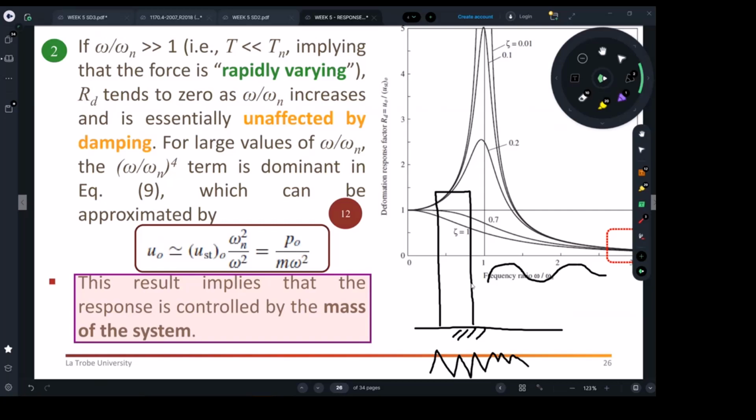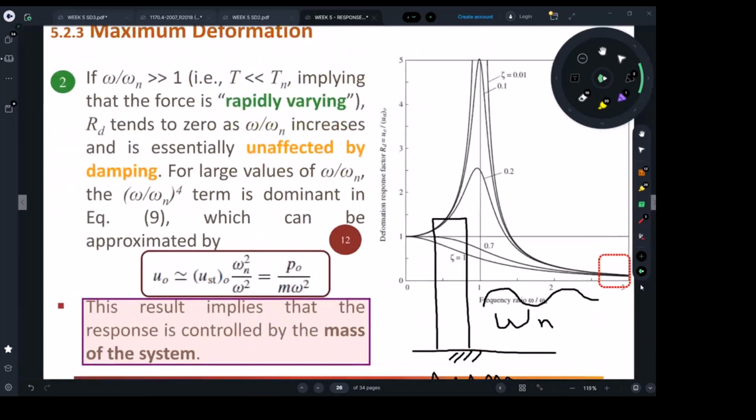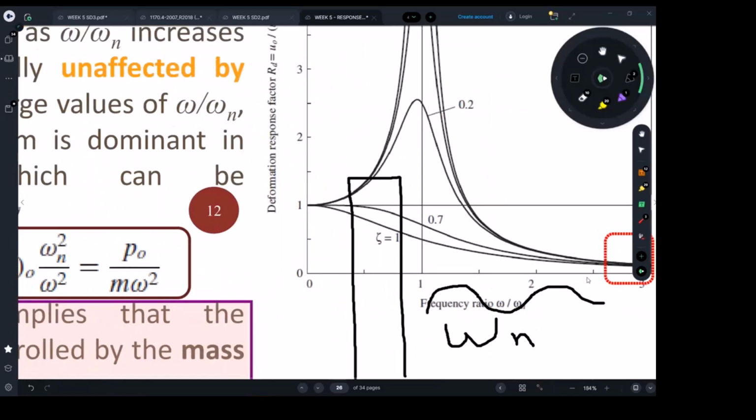So you've got a building whose natural frequency omega n is kind of gentle, and the forcing frequency is very high frequency. In this case, we're going to be situated here within the frequency factor curve, right, because we have a very high ratio.